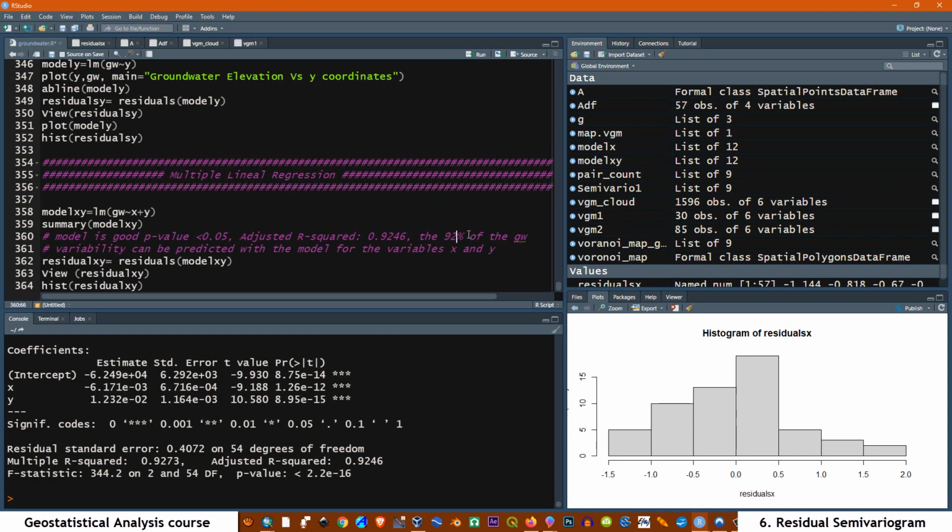We have to be aware that it's not the final model, that it is not the groundwater flow direction plane, okay? That it's a trend that we want to remove from our data. But even though it's not the real groundwater flow direction, the plane is really good to predict the groundwater flow direction, okay? In a 92%. That's the point. And that's why we can use a first polynomial to remove the trend from our data.